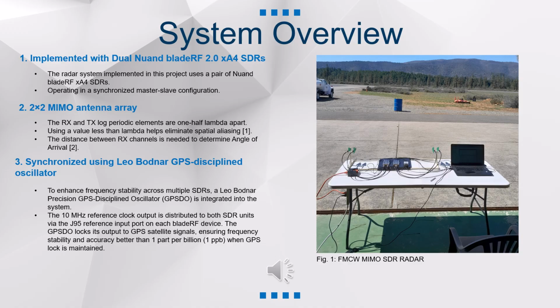This system uses dual software defined radio architecture to perform distance estimation through the reflection of a chirp signal. One software-defined radio is responsible for transmission and the other is dedicated for reception. The separate modules are synchronized using a shared reference clock and trigger.